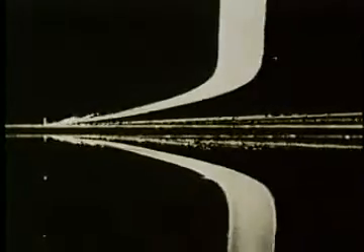The velocity throughout the boundary layer is less than that in the free stream. There is no slip between the plate and the layer of fluid immediately adjacent to it. At the plate, the relative velocity is zero. This is the no-slip boundary condition of viscous flow.